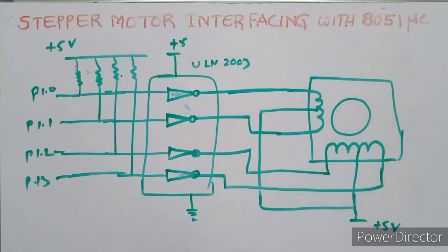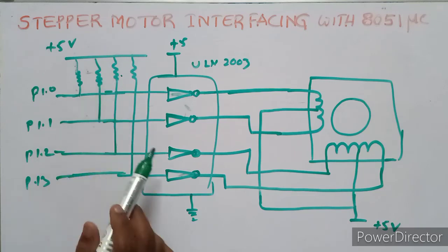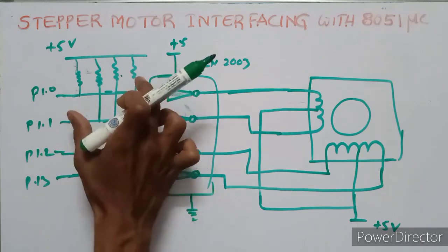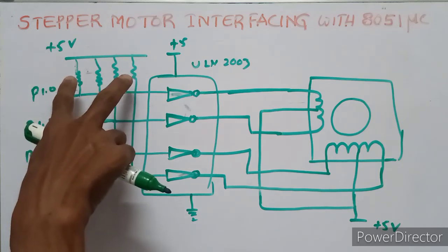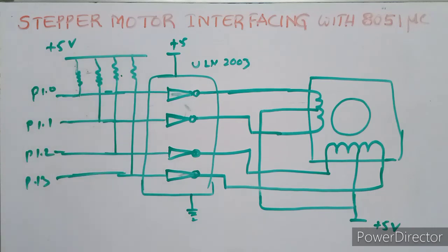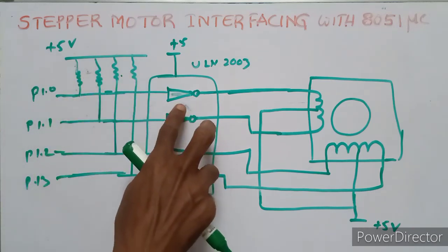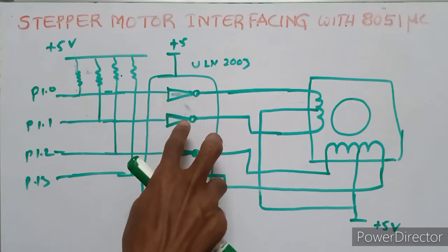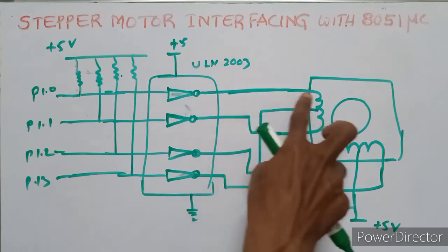Use an ohmmeter to measure the resistance of these 4 leads. This should identify which COM leads are connected to which winding leads.